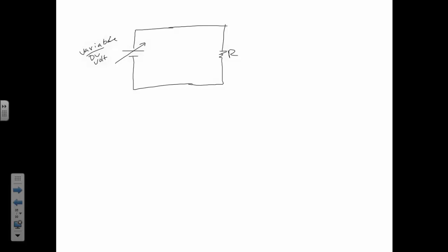So this is a 39, and the next number is the multiplier, brown, which is 1. So that's 10. So 39 with one zero is 390, and the gold means how accurate this is: plus or minus 5%. So it could be anywhere within plus or minus 5% of that.